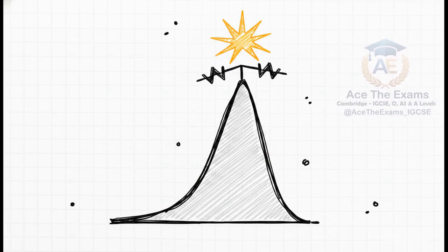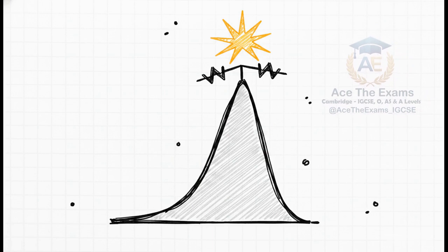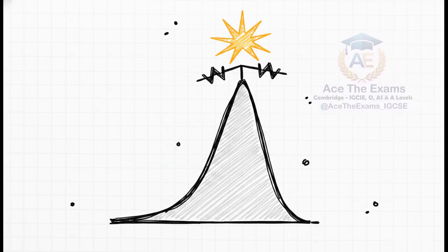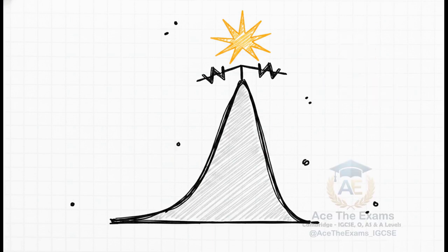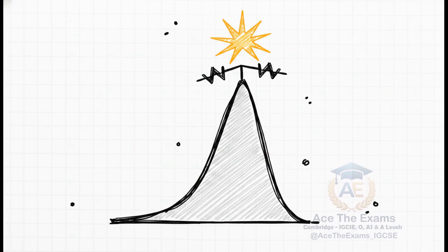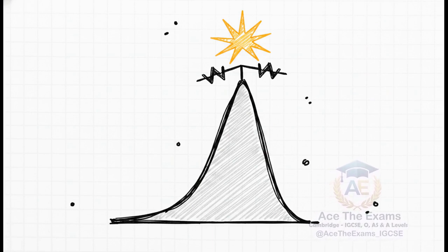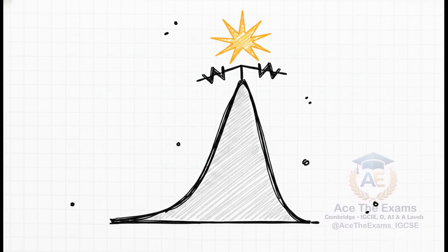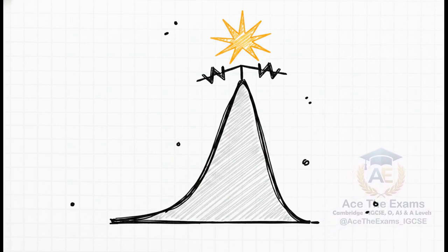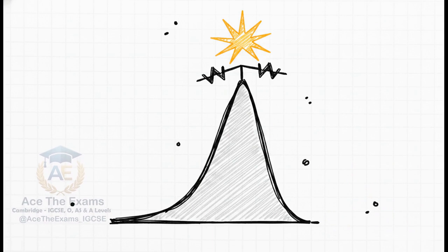What does that mean for us? It tells us that a battery hits maximum power delivery under one very specific, honestly, mathematically beautiful condition. It happens exactly when the external load resistance, that's capital R, perfectly equals the battery's internal resistance, lowercase r. Think about it. If your external resistance is too low, you're wasting most of your power just fighting the internal friction of the battery itself. Too high, the current drops so low that, again, barely any power is delivered. That sweet spot, the absolute peak, is right when capital R equals lowercase r.